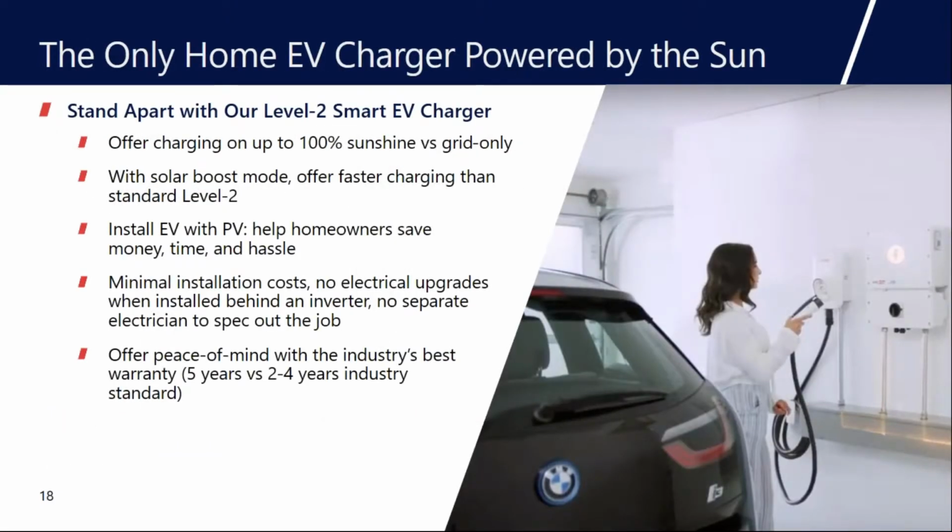The EV charger, again, is a little bit different. As you can see in this photo down here, this is a 6x6 inch gutter. Anytime you're installing the Energy Hub with a backup interface and any of the ancillary devices and batteries, I strongly recommend you use a gutter. The gutter will really help with your transitions between walls.